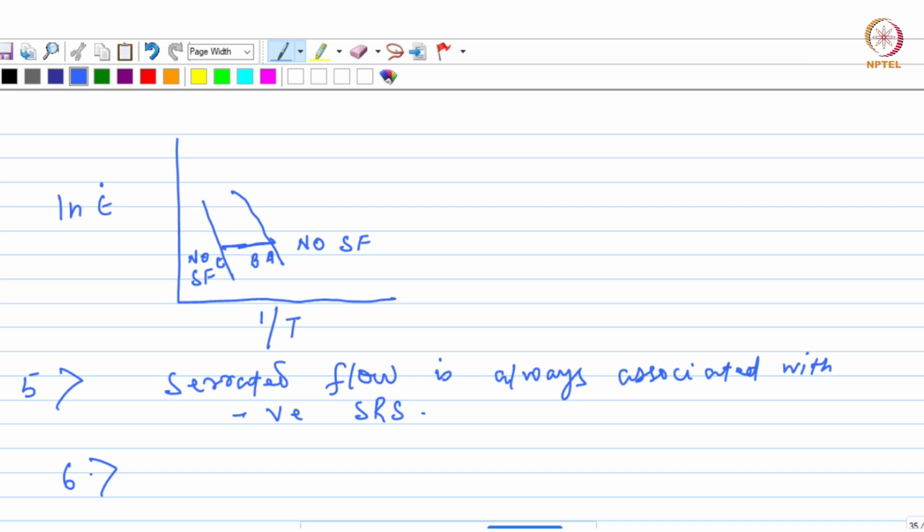And there is a significant difference between steels and aluminium alloys as to when this dynamic strain aging will start. This is because the alloying elements are of different types in steel and aluminium alloys.